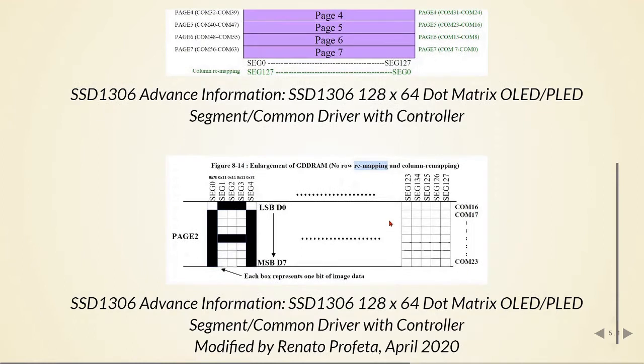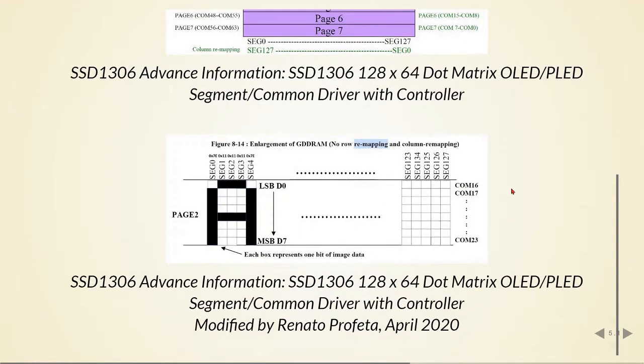The eZDSP examples come with very limited implemented characters, so I will try to get some OLED fonts. The SSD1306 has some fonts that we can use with some adaptation.